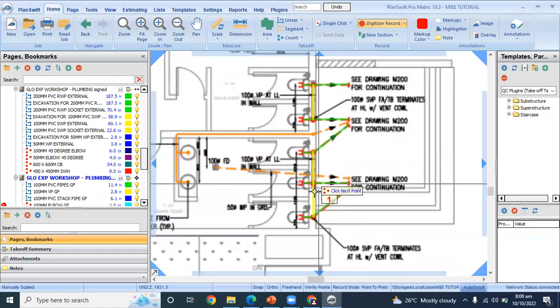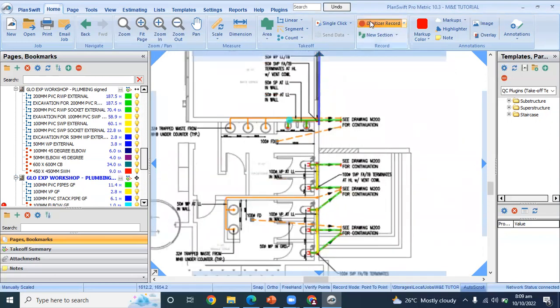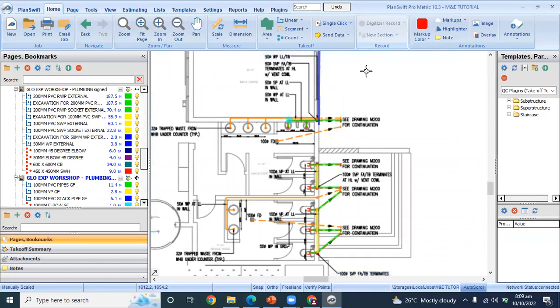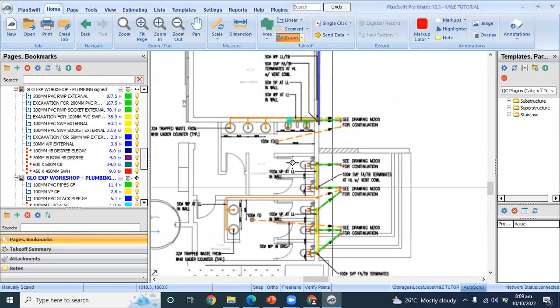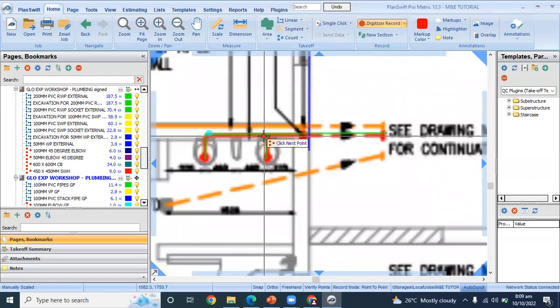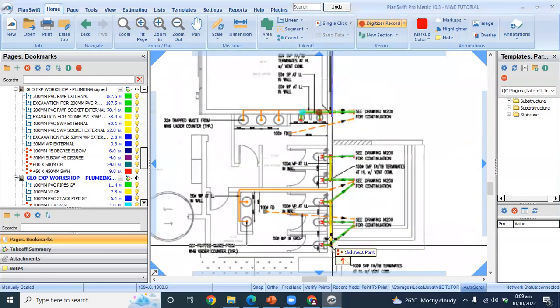Where again do we have elbow? We don't have elbow elsewhere. Okay, so we have T, equal T. So 100 mm equal T ground floor. Click OK. So we have 1 equal T here, since that's the only place we have 100 mm equal T.